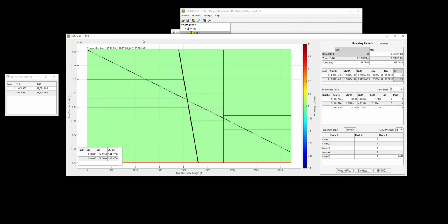Okay, so now we can start filling in the resistivity values. We have everything where we want it. So I'm going to start off in here. The top layer is, so we'll do the RH first. And notice that if you're just changing one, it might be easier to set the resistivity by the block. So I could set this one to 2 and this one to 5, which is what's indicated in the model.